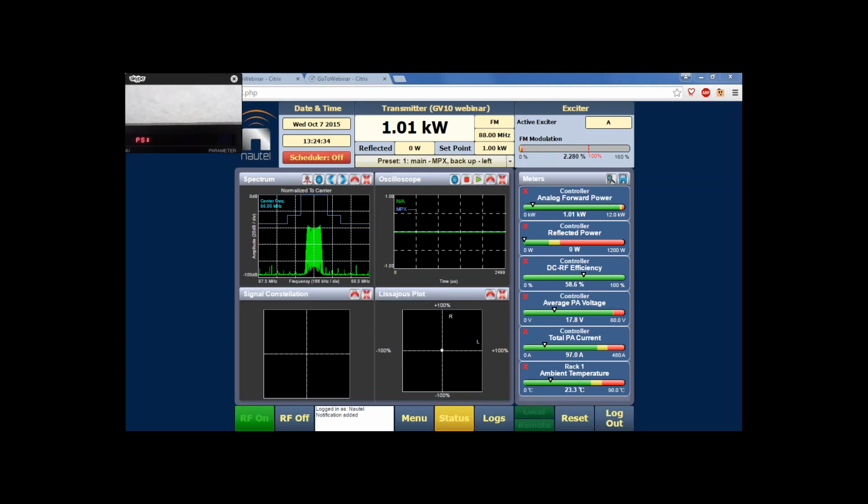So I've just killed the mono left signal. So in about 10 seconds, the mod loss timeout will kick in and bring up the USB signal, which now it's playing. Right now we have a USB MP3 that's a 15-second clip. I've just now turned the mono left back on, so when that 15-second clip ends and then there's silence, the mod loss timeout will click back in again and search for something on preset 1.